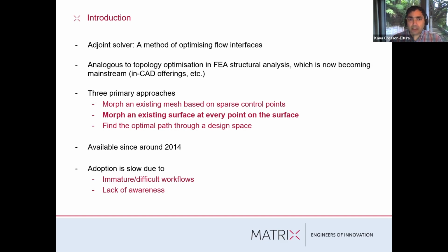And I've applied it to giant structures as well on submarines and gotten lots of weight savings out of that. But it's analogous to that in that you're letting the physics guide the solution. So instead of you prescribing the geometry, yes, you prescribe some starting geometry, but then the solver actually uses the physics to guide what that geometry should look like. So it's an optimization technique.